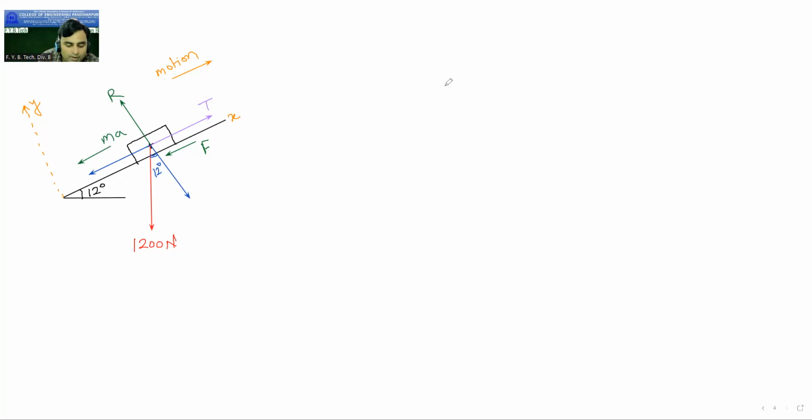After this free body diagram, if I resolve the weight, the components become 1200 cos of 12 and 1200 sine of 12. Now consider the y-axis as the reference axis and the forces parallel to it.